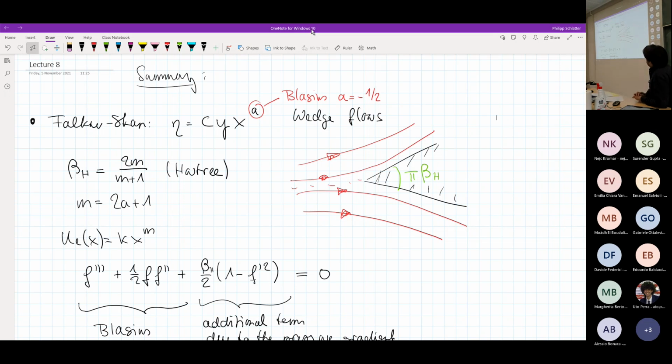But as usual, I would just like to summarize very briefly what we did yesterday. If you remember, we looked at the Falkner-Skan equations, or the family of similarity solutions. And I guess most of the time we actually spent on defining the conditions that are necessary for a Falkner-Skan solution to be a valid similarity solution. And kind of on the way, we realized that the family for Falkner-Skan is obtained when we have the parameters A, beta, and M to be in a specific way.